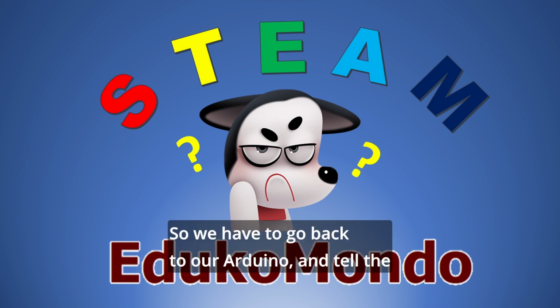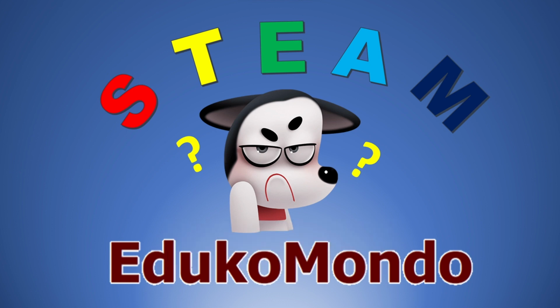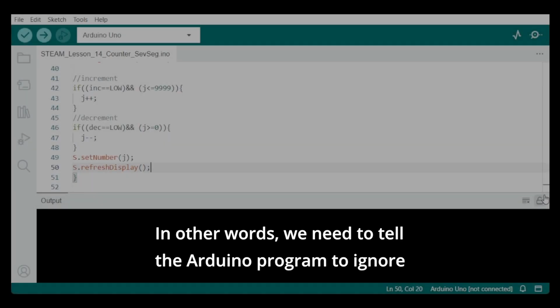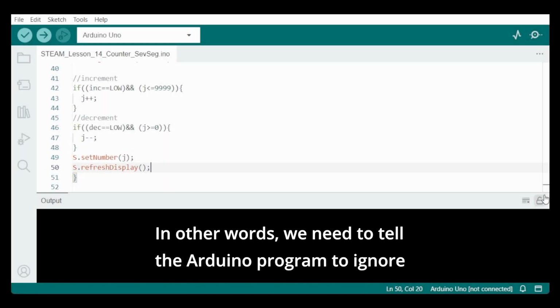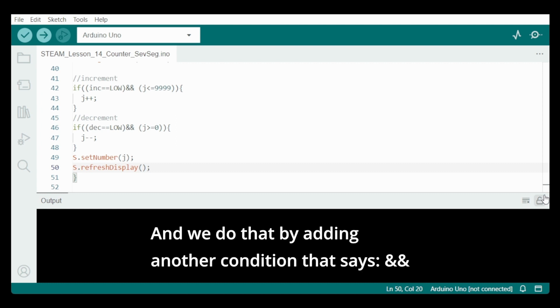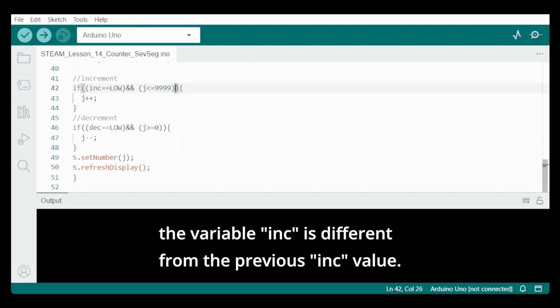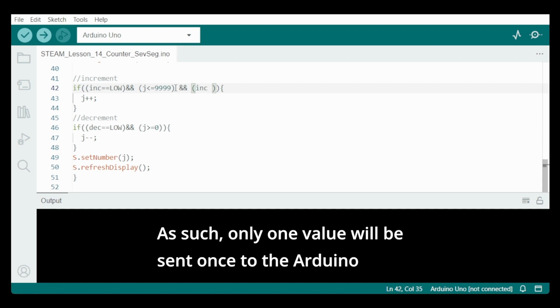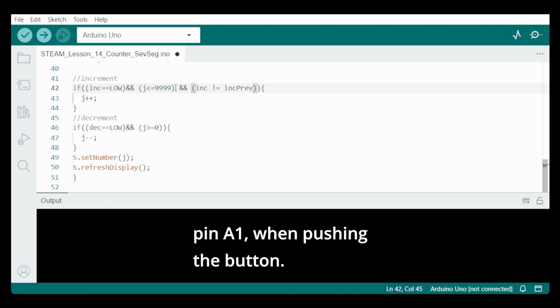So we have to go back to our Arduino IDE and tell the Arduino that only one impulse has to be taken into account. In other words, we need to tell the Arduino program to ignore a second pulse. And we do that by adding another condition that says "n" and the variable inc is different from the previous inc value. As such, only one value will be sent once to the Arduino pin A1 when pushing the button.